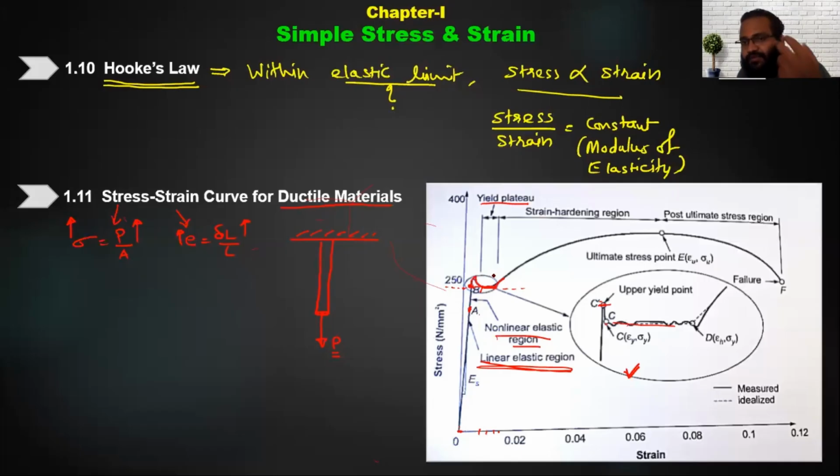आफ्टर yield point if you deform the material, ठीक है, तो क्या होगा, यहाँ पे you can see the stress value increases. Now this stress value increases because of increase in the additional load as well as decrease in the cross section of the material. तो अगर मैंने ये वायर ऐसा था, ठीक है, तो अभी वायर क्या होगा, एक पर्टिकुलर रीजन जहाँ पे भी इंटरनल वीक होगा वायर, उधर वो वायर अभी क्रॉस सेक्शन रिड्यूस करना चालू करेगा, उसका क्रॉस सेक्शन ऐसे कम कम होना चालू करेगा. दिस वी कॉल नेकिंग, राइट.